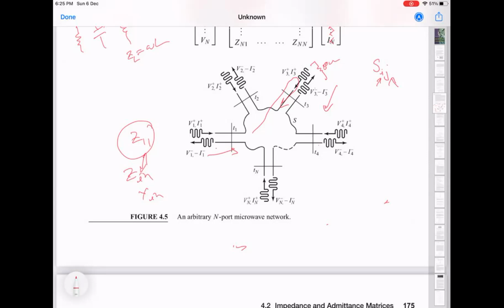We haven't looked at this device in detail, but there is a device called a splitter, which will take an input signal and basically give you 3 dB less power on both outputs, so that it's approximately half the power. It's called a 3 dB splitter. If you're measuring this object and checking whether you get 3 dB loss going this way, it's extremely important that you keep this one terminated with 50 ohms. Otherwise, the other part of the power which goes in can come back and do something weird, like coming back into here. All kinds of things are possible.